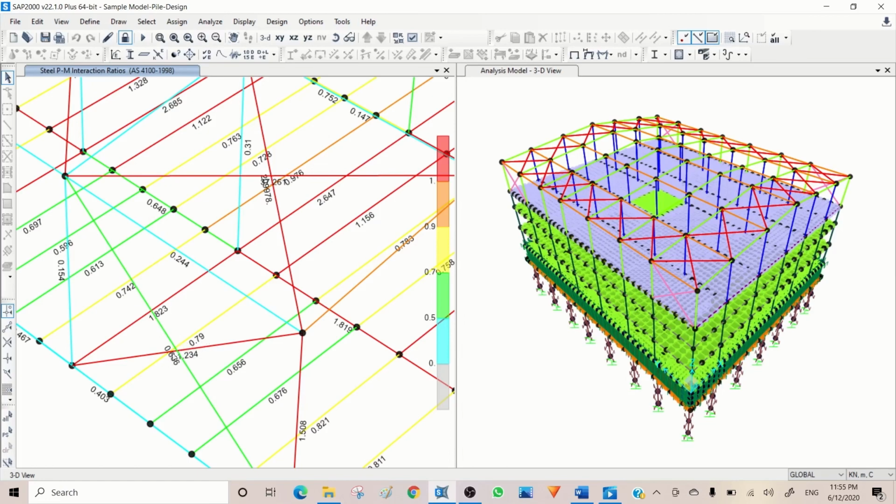So for a brace, what you need to always check is the effective length ratio for out of plane and in plane. The same for roof brace. The difference between roof brace and vertical brace is generally roof braces are designed for tension. That means you need to define those braces as tension only members, and you need to do nonlinear analysis for tension only members. We don't have this license at the moment, so we cannot do a nonlinear analysis.